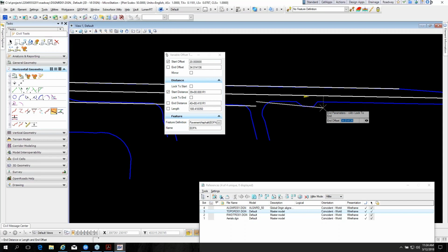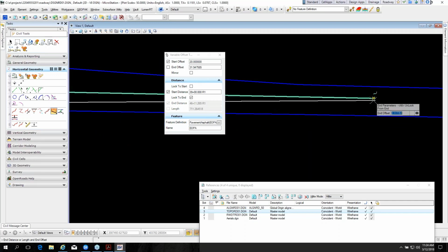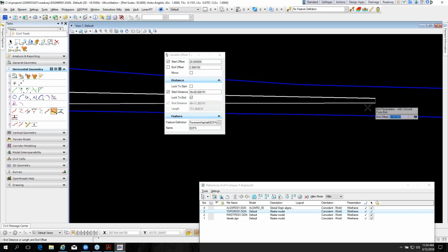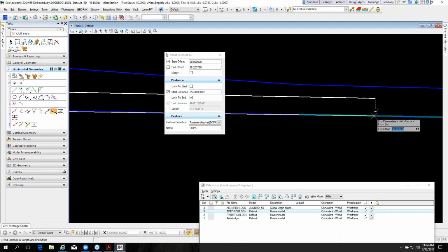And then I want to go ahead and tab Alt, and that will lock me to the end of this stationing. And see how this got checked here and the length? So now I can just do a nearest snap to that point, or to this asphalt milling line that we put in there, is all we're doing on this tool.